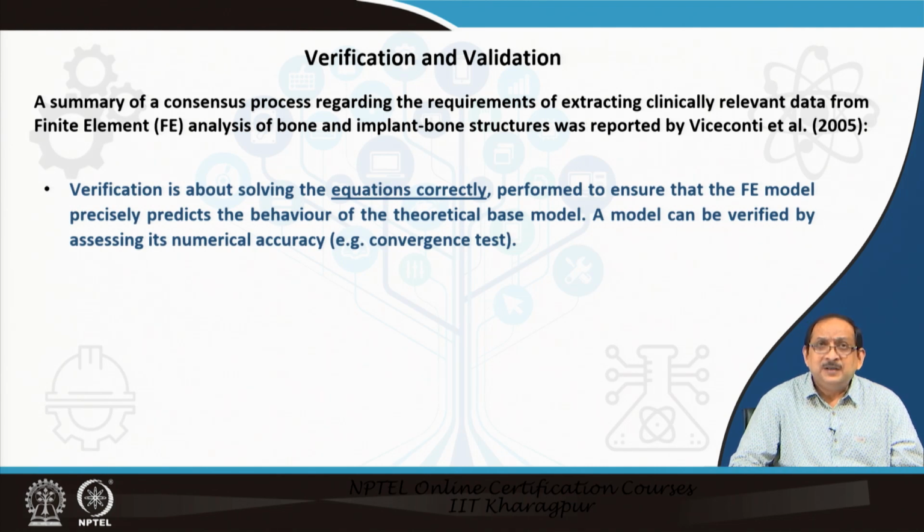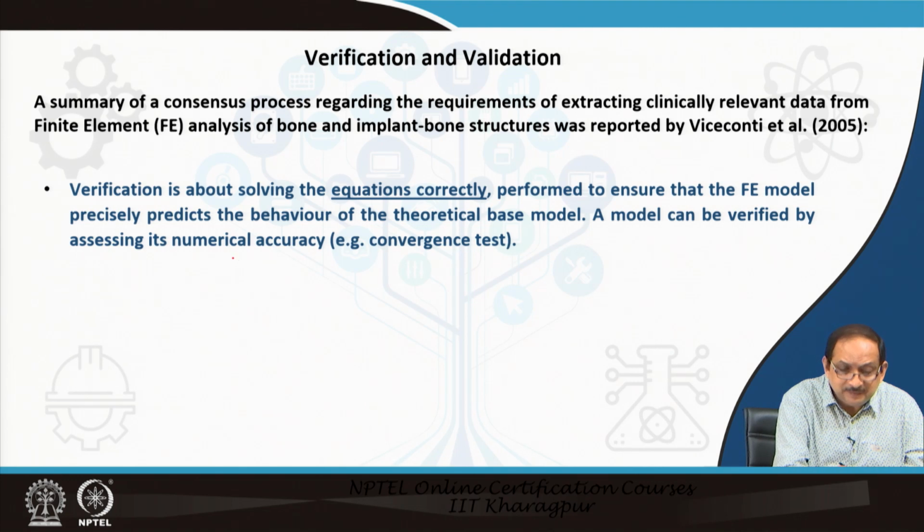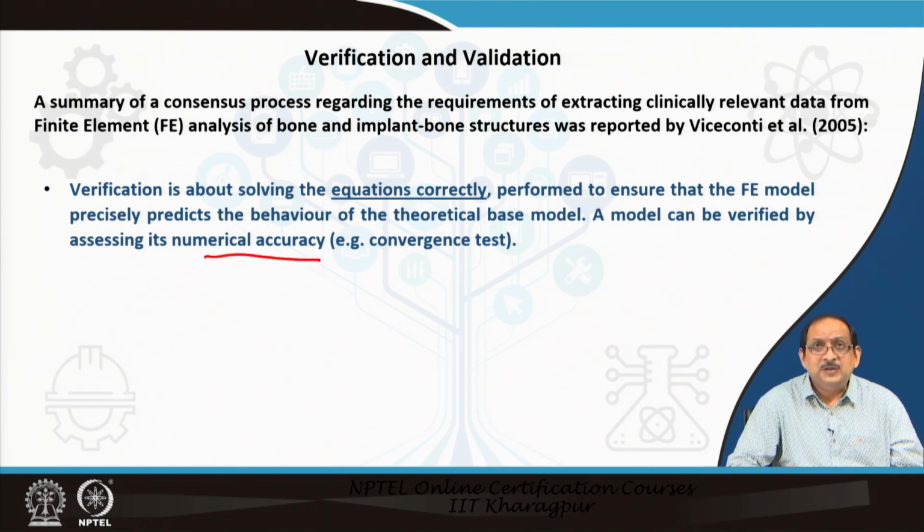Verification is about solving the equations correctly. It is performed to ensure that the FE model precisely predicts the behavior of the theoretical model. A model can be verified by assessing its numerical accuracy, for example, using a convergence test.